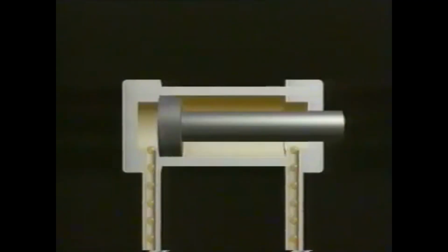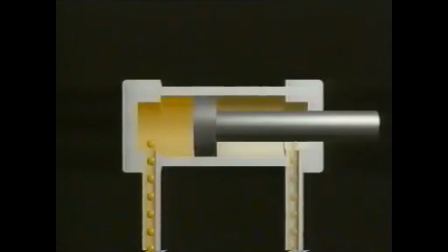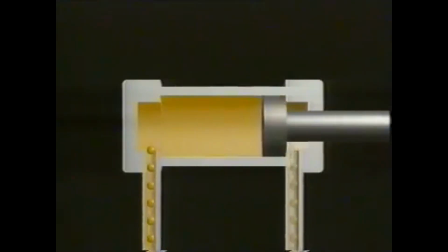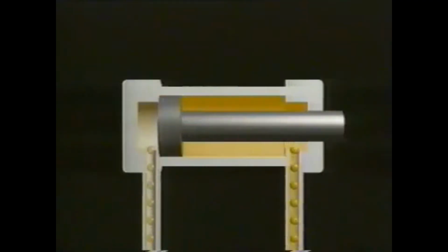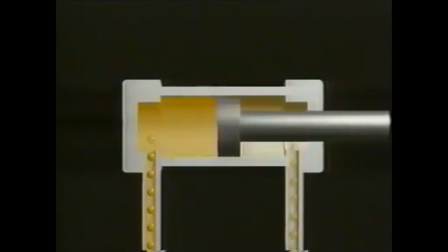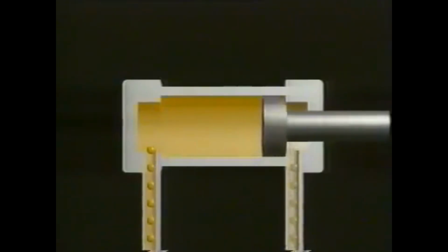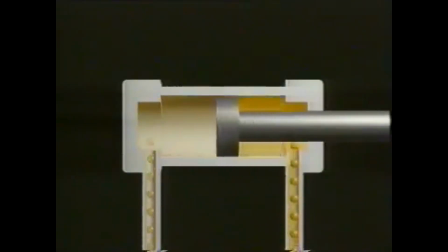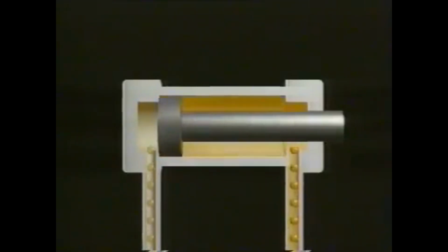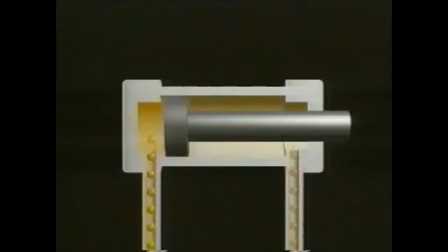On the other hand, the flow rate being equal, half the chamber volume on the rod side is filled with oil in half the time, so the piston retracts at twice the speed. The flow rate of the discharged oil is also twice as high because double the amount of oil must be discharged in the same time. This causes back pressure to develop. These laws must be taken into consideration when choosing hydraulic cylinders.